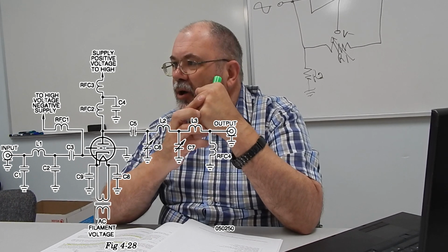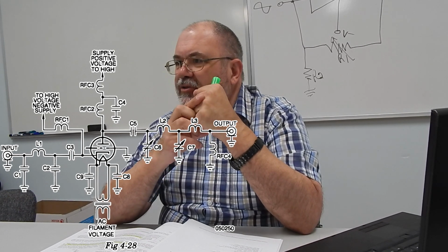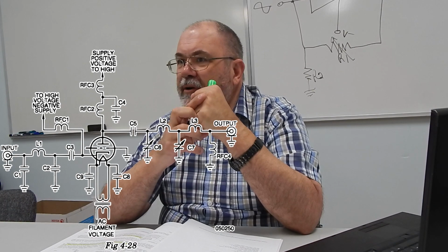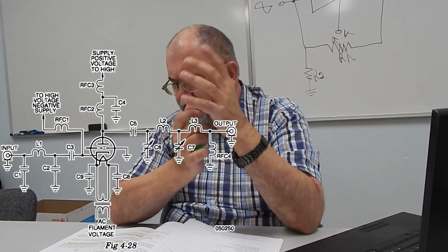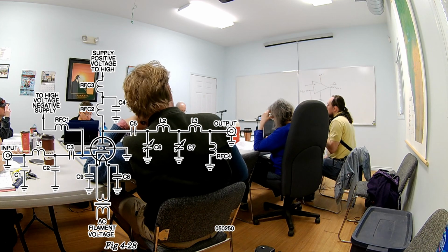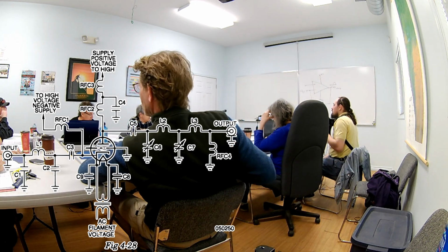And depending on what kind of antenna load you put out there, you may just throw up a random wire in the yard, or you may have a commercial Yagi or a commercial vertical or something like that. Every frequency you're going to go on, the impedance of the antenna is going to be slightly different. So these tuning controls give you the opportunity to match this up so you get maximum power transfer out to your antenna. It's basically an antenna matching network. So that would eliminate a separate tuner.